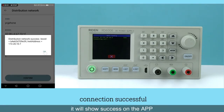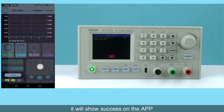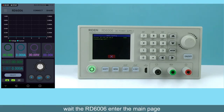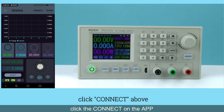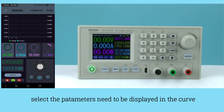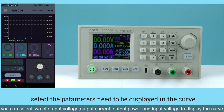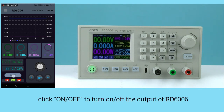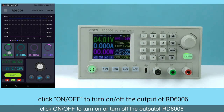It will show success on the app. Wait for the RD6006 to enter the main page. Click Connect above. You can select two of output voltage, output current, output power, and input voltage to display the curve. Click On/Off to turn on or turn off the output of RD6006.